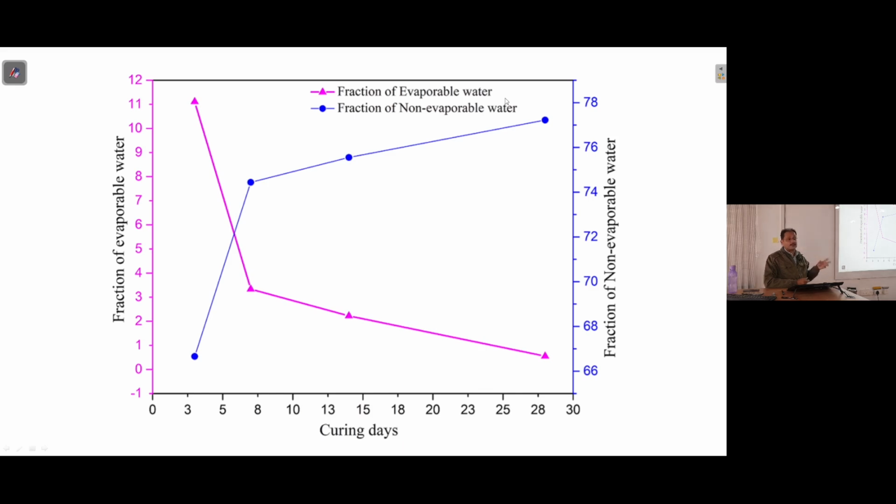This hydrated product has both. It has some amount of water which, if you heat up, can be evaporated. At moderate heating, not very high temperatures, this evaporable portion will leave the material. But this non-evaporable fraction is closely knit into it.